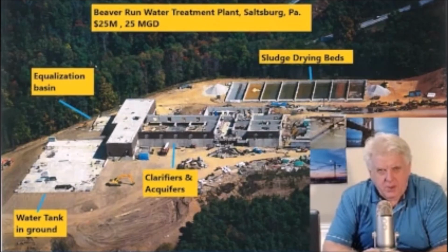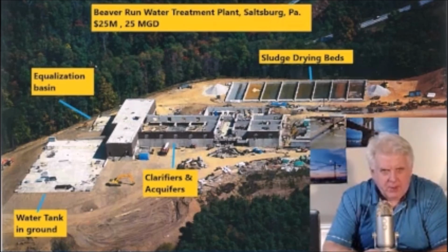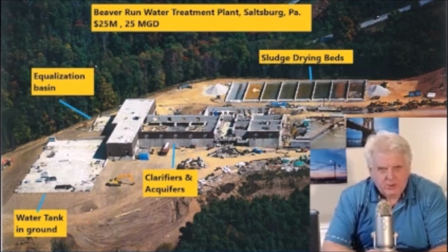So we met with the owner and the engineer of record and the value engineers on this particular item, and we wanted to know why the engineer of record's design was such. And he came back and said, yeah, we could do that. However, our specification calls for us to build the tank freestanding and then fill the tank with water and then wait 30 days to see if there's any leaks through the concrete. And so presented like that, the owners rejected that value engineering item.